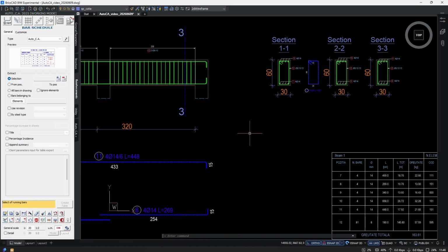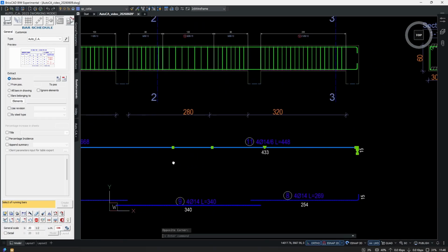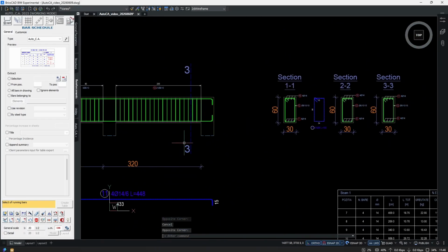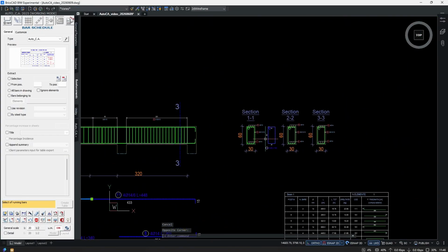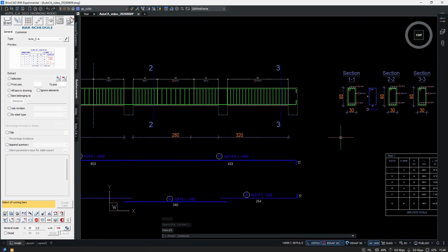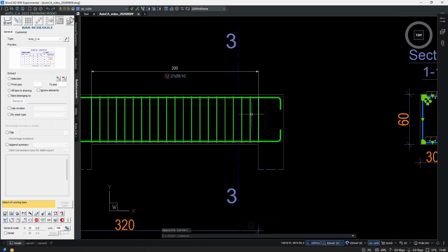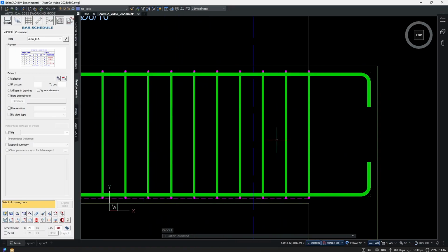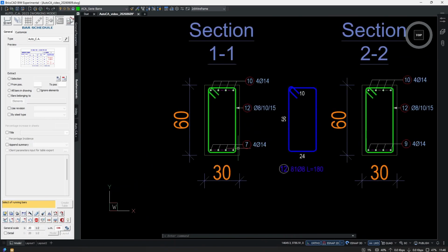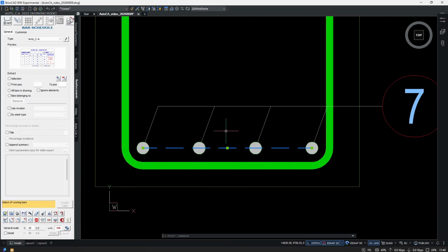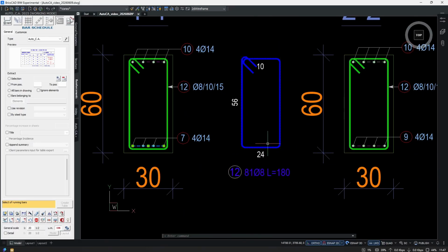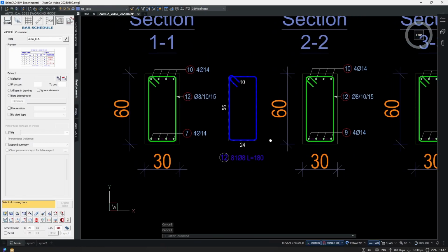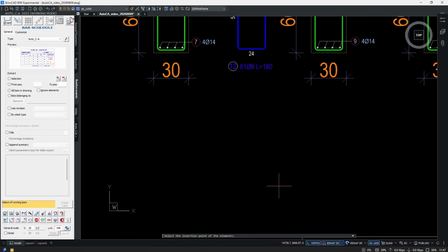The key is that the primary element is the outside bar, always the outside bar. Be it the longitudinal bar or stirrup, they are both outside bars. The inside bars, the green ones, are only for display purposes. However, stirrup distributions and section bar distributions are internal bars that increment the quantity of the outside bars if they are linked. Therefore, if you only copy the outside bar, you get a brand new bar that counts as one